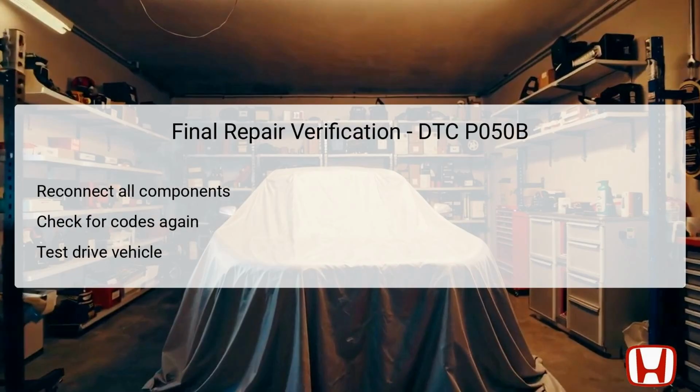A thorough test drive is also recommended to ensure the vehicle is functioning as intended, particularly in cold starting scenarios. Monitor the engine's performance closely during this drive to ensure any previous symptoms associated with the P050B code have been resolved. If everything checks out, you can confidently conclude that the repair was successful.